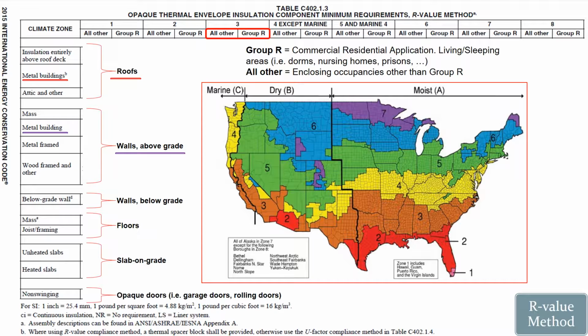So you may have a metal building that would use open bar joists, and that would include a metal decking laid on top of the bar joist, and then you would have continuous insulation, maybe rigid board, set on top of the metal decking, and then you would have your roof membrane covering.